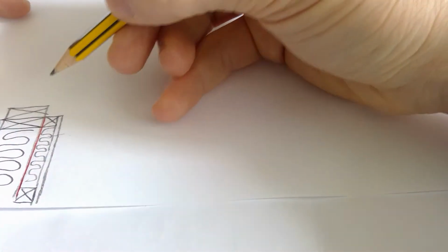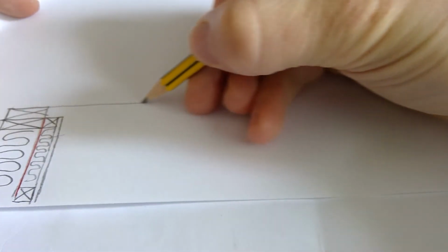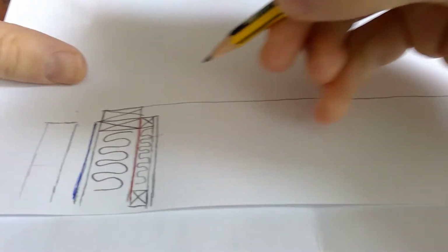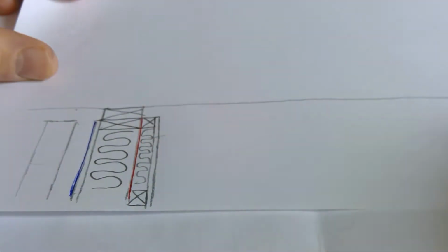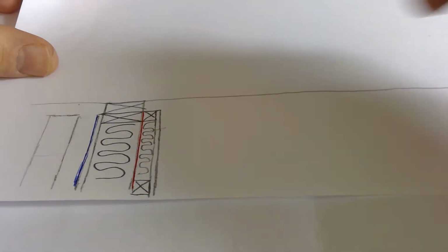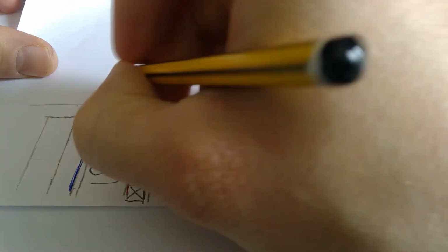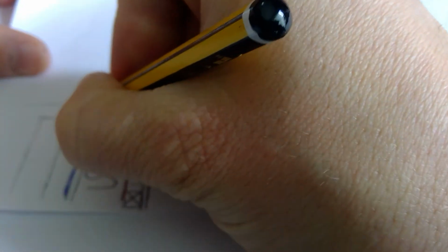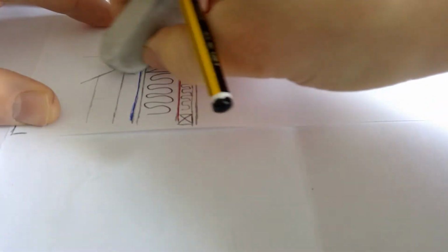Alright, now at this point I would lightly draw across the space for a joist. Extend that on for the moment. Alright, the pitch of the roof, the question tells us, is 30 degrees, so you're going to go up here. Now remember, it does not cut into the wall plate, the truss just rests down on top of the wall plate when it comes to a truss roof. So go off at your 30 degrees. There. You can see it cuts into the wall of my sketch a little bit here. I think in the actual solution it doesn't, but I'll rub that out anyway. If you want to make this your wall go a little bit lower there, that's fine.